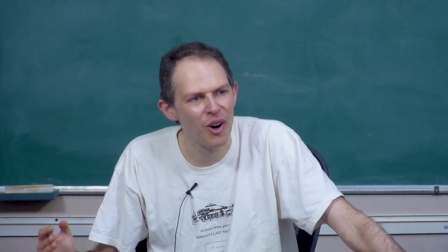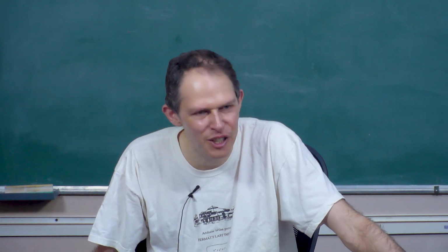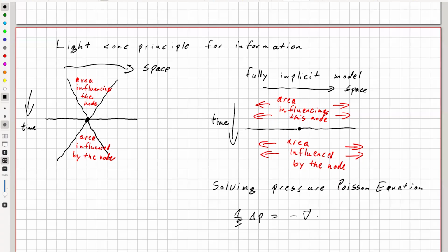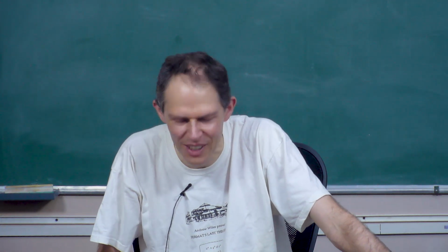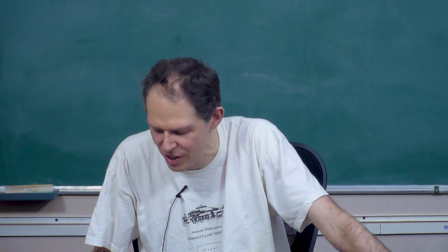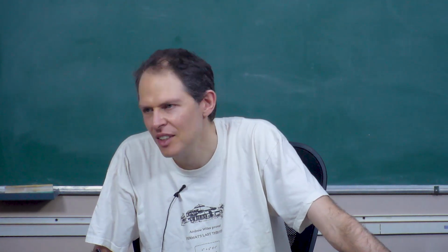The thing is, the Navier-Stokes equation is an equation on the velocity and on the pressure. You need the pressure in order to solve the Navier-Stokes equation. And the equation that you do this with, which arises from the Navier-Stokes equation under the condition of incompressibility, basically looks like this. I guess you are familiar with these operators that are also here. The Laplace operator on p, so the second derivative of the pressure, is this strange thing here of the velocity.